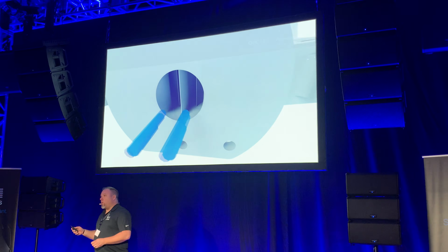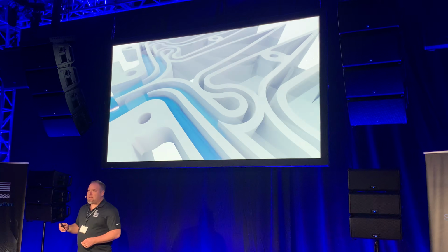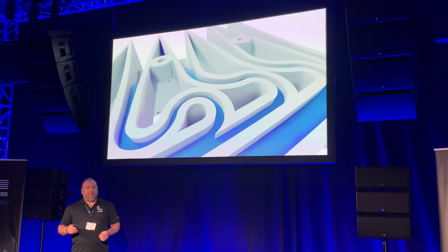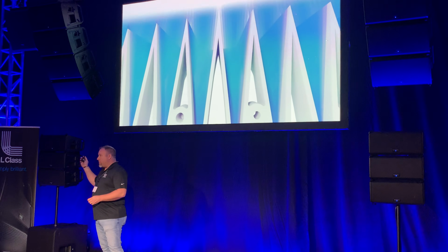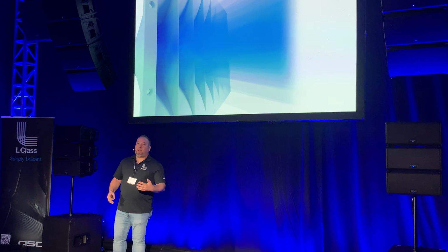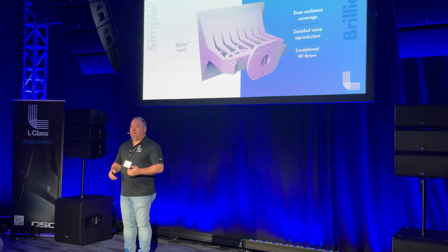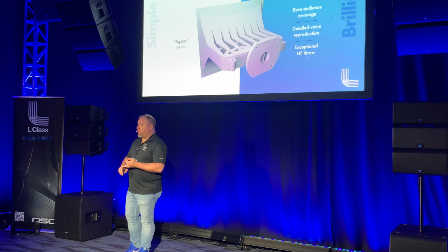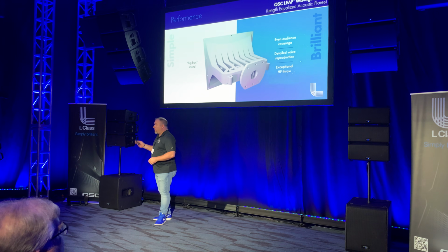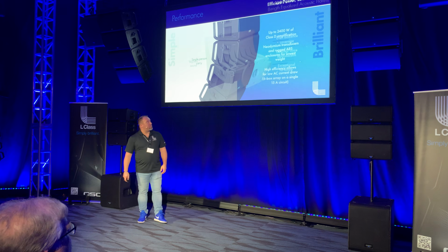The way it works is there's a channel series that funnels the high frequency through to the exit of the high frequency driver, or the high frequency waveguide, and makes sure that all that high and mid and upper mid is in alignment as it leaves the box. So you're going to have increased output, increased intelligibility, and increased performance from a much more compact size box.